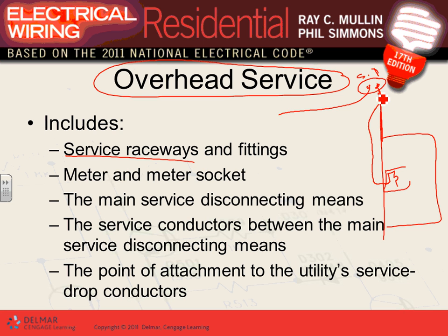So you have to have a service raceway here with all the fittings that come with it. You have a meter socket. You have a meter. Here's a meter here. Main service disconnect means, here's my main service disconnect means, that's the first circuit breaker that you land on. Service conductors between the main service disconnect means. Service entrance conductors is right here. This is service entrance conductors.